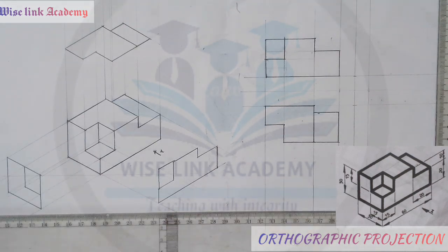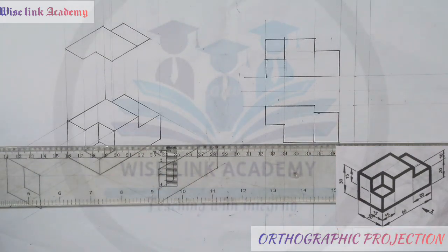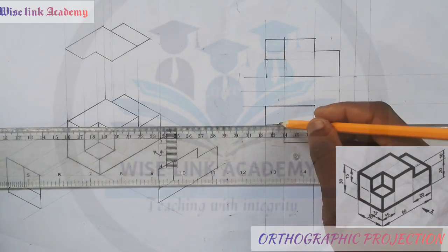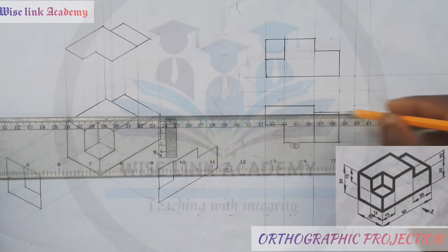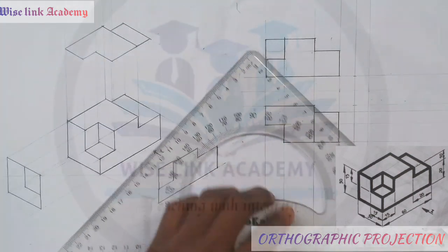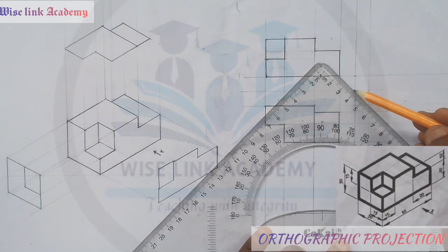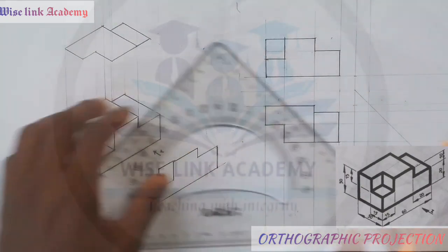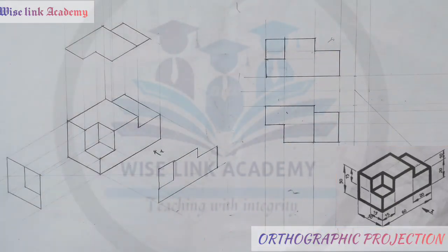So let's draw the side view. I will extend all the edges this way, right? With the help of my 45-degree set square, I'll place it at this center here and then extend it downwards this way. Having done with this, I will take my set square.